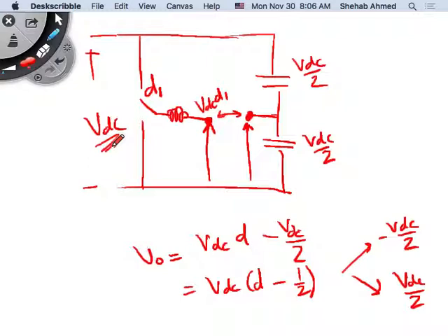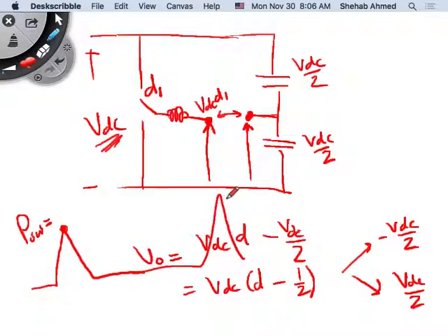And we saw that if you increase the DC voltage that the switches have to block, how does that affect losses? Remember our switching loss? Remember these triangles that we drew? What was the peak value of the triangle, for the turn-on and turn-off losses? What was the peak value here for the power loss? Exactly, it's V, the voltage that the switch is blocking, and I, the current that the switch is conducting, right? So if we're blocking double the voltage, then it's going to affect switching losses, right?